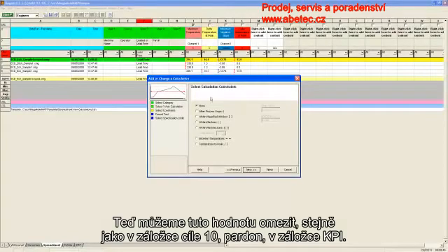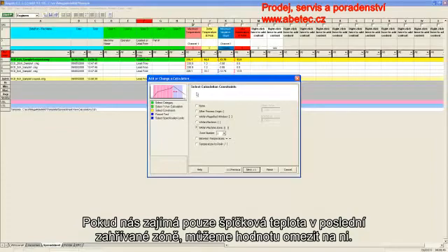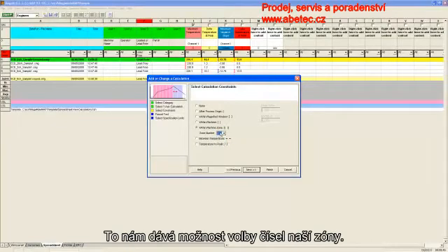And then we can constrain that value just like we can in our Target 10 tab, or KPI tab, excuse me. So we can constrain it to after the process origin, to within a magnified window, within a machine model, or to a specific zone. So if we're only concerned about peak temperature in the last heated zone, we could constrain it to that. Gives us a choice to choose our zone numbers.